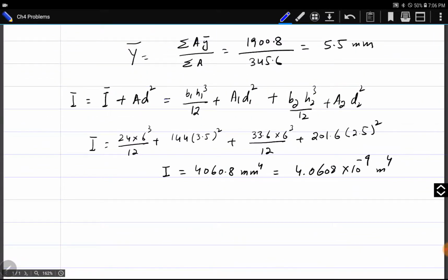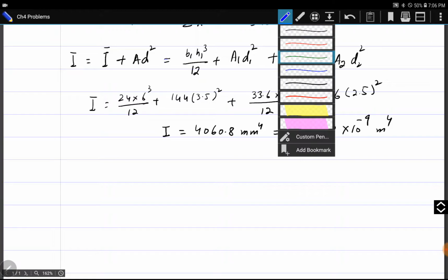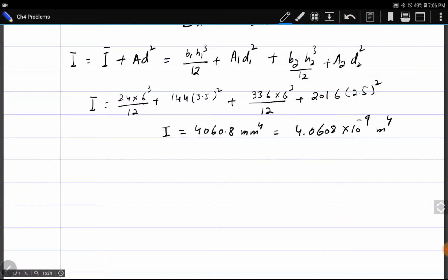Okay. First we will find maximum stress in aluminum. In aluminum, the maximum stress will occur at its outer surface: M C of aluminum divided by I. C is the distance on neutral axis from the outer surface of aluminum. Moment is given 35 Newton meter.